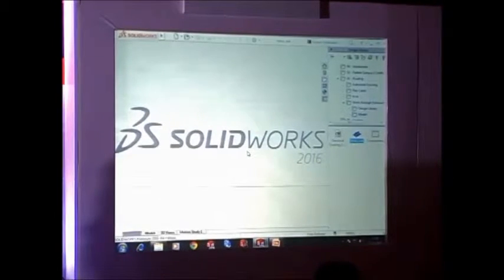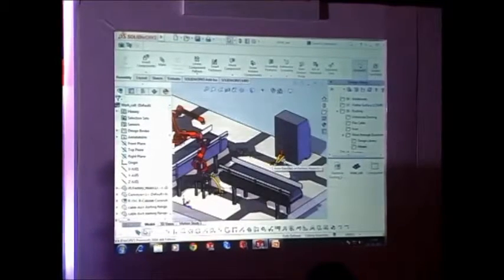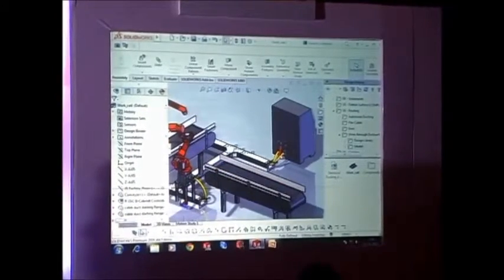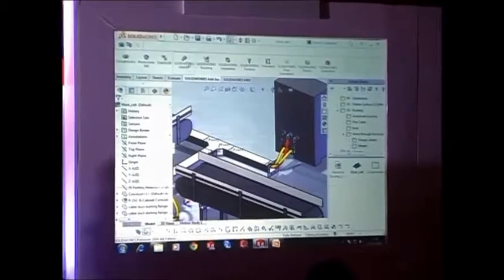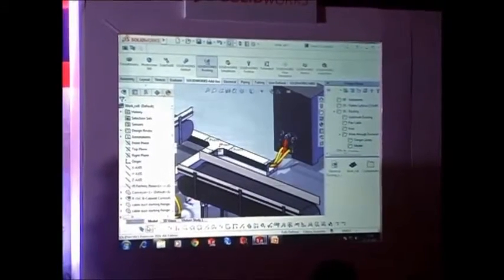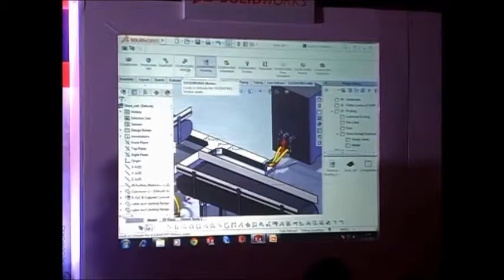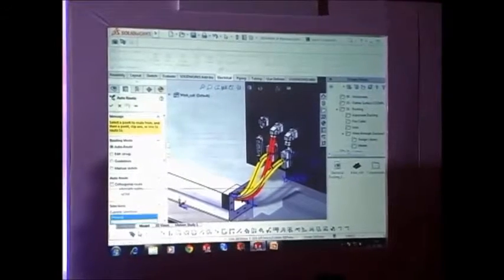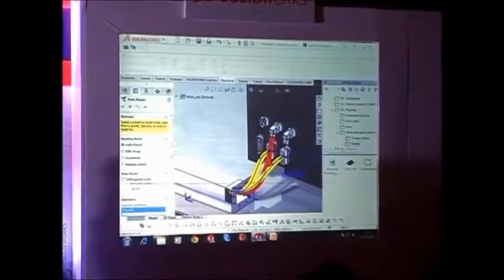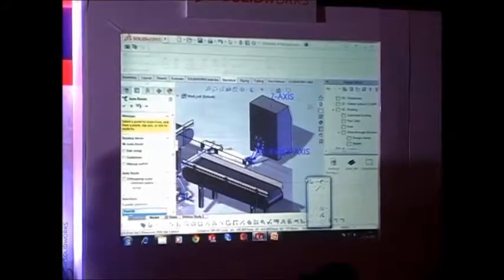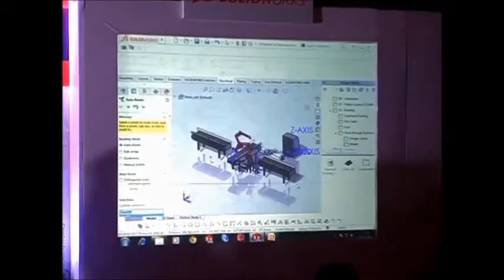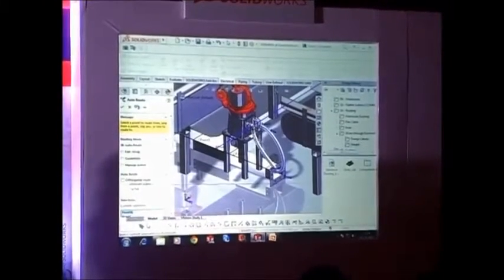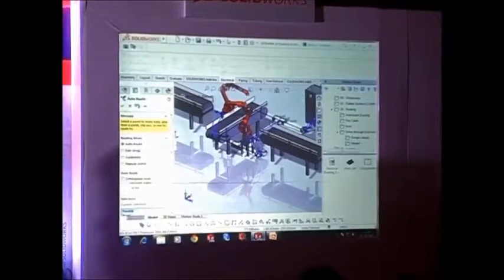Many assemblies follow the duct route to run the cables. Here we can easily add the connection between the duct and the control panels. By just selecting the control panel and the inlet of a duct, it easily forms the connection between both. The same applies to the outlet of the duct to the terminal connector. In a very easy way, we can create our routes.